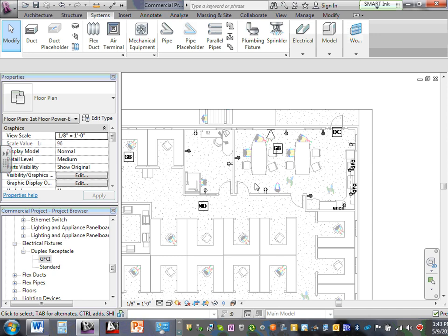All right, did you guys drop a couple of these? Now, unlike CAD, guys, Revit is supposed to be intelligent software. So when you circuit, you have to circuit to a panel. Do we have a panel yet? We don't have a panel. So we throw up the receptacle. We're going to drop one of these. Let's go drop one of these.